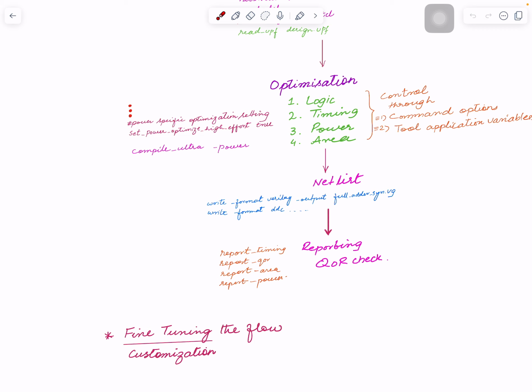You really want to analyze thoroughly. You want to analyze every aspect of timing, general QoR, like timing, power, area, and all that. How is area, how is power? There are so many commands that you can use. There are some generic ones that people use for signoff. So you need to have those anyway, but then you can have a lot of additional scripting or reporting just to save the information, to report the state of the different optimization, and you can store it in a different file.